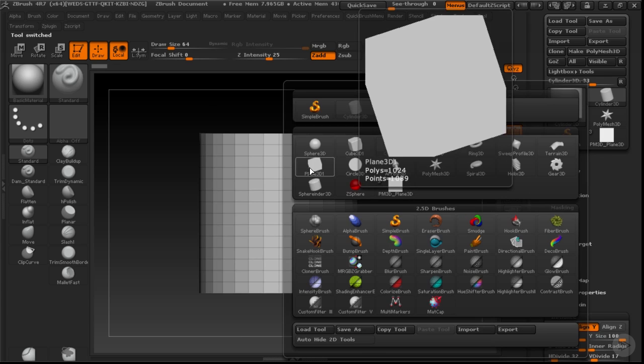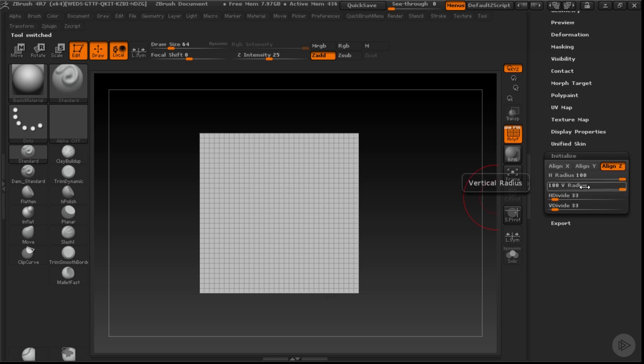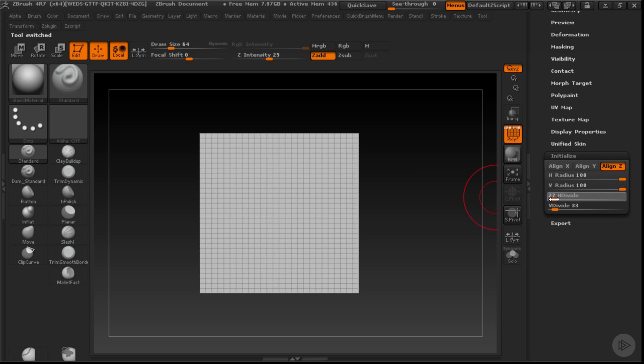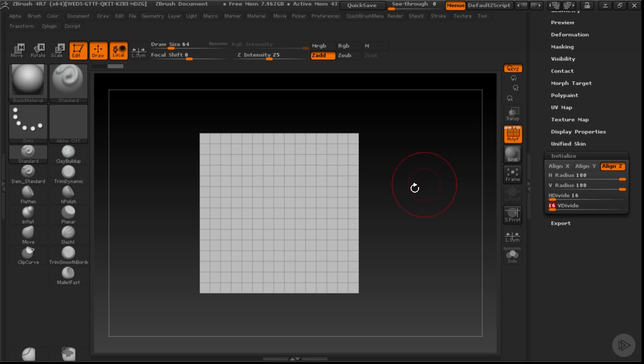When you start off with an object straight up without having to append it, you can change some of the properties of it. So for example, this is divided 33 times. If I start to pull this down, there are less divisions in this. In general, as a rule of thumb, when you're dealing with big shapes and forms, it's easier to work with fewer polygons than more polygons, just because it allows you to deal with big shapes very easily without the brush strokes kind of taking over and having to fiddle a lot with little small details.